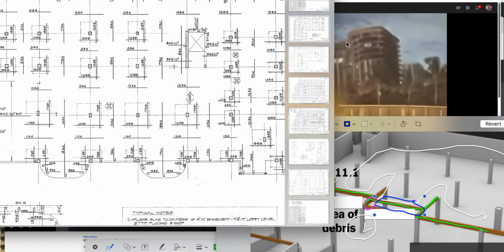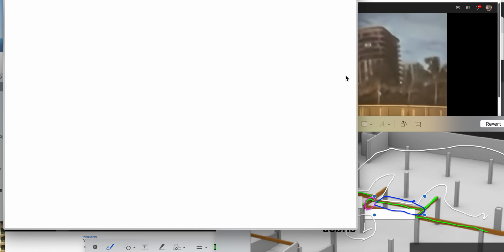This is from the top down, 8th floor and top floor down. This is from the bottom floor up. With some failure in the floors up, the interaction across here, but mostly you can see it's already sheared apart from the roof line. The roof line is sheared apart, and there it is there, which is very telling in itself, saying that L has already failed and has significantly dropped down into the garage area.